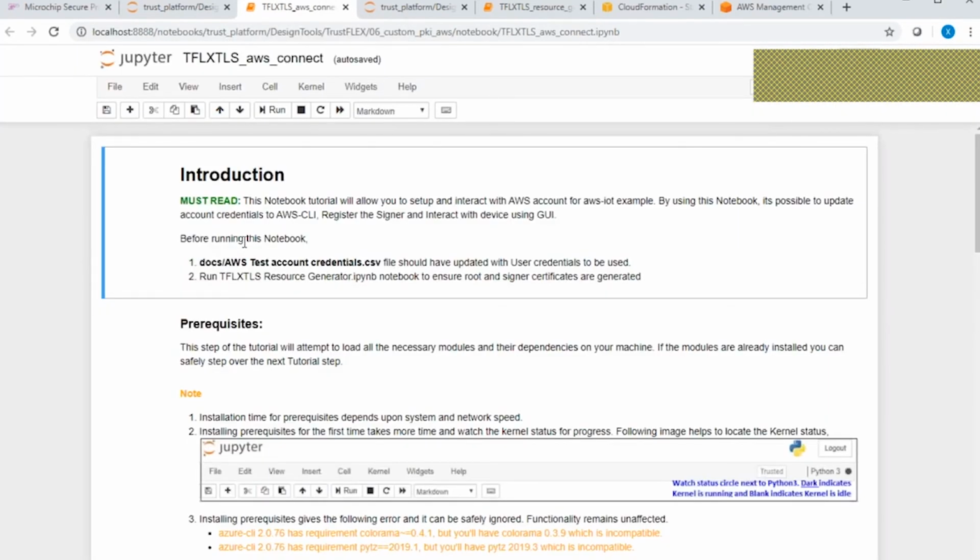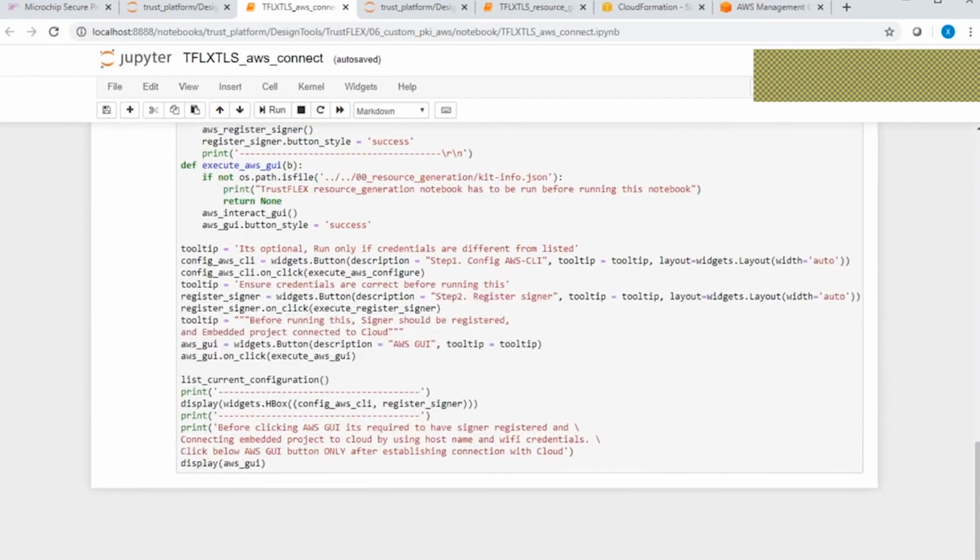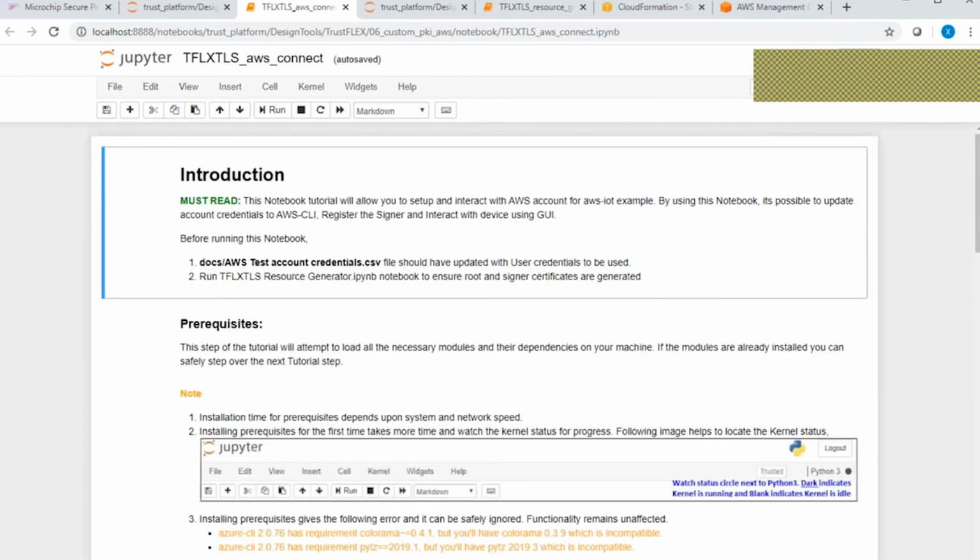The first thing you want to do is create that certificate chain. And this Python code is prototyping a certificate chain for you to start prototyping. You don't want to use that certificate chain for production at all. So that's once you have your credential, what you'll be doing, the tool will also help to provision them into the board that we showed there. And it takes literally less than a minute. You run the executable, it loads automatically the credentials into your board and you're done. If you want to stop at the secure element level, you're done.